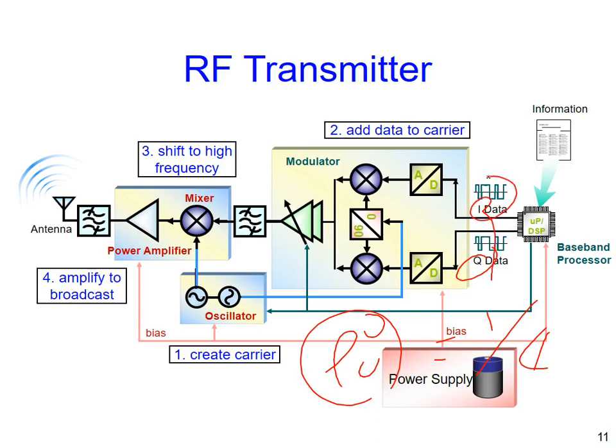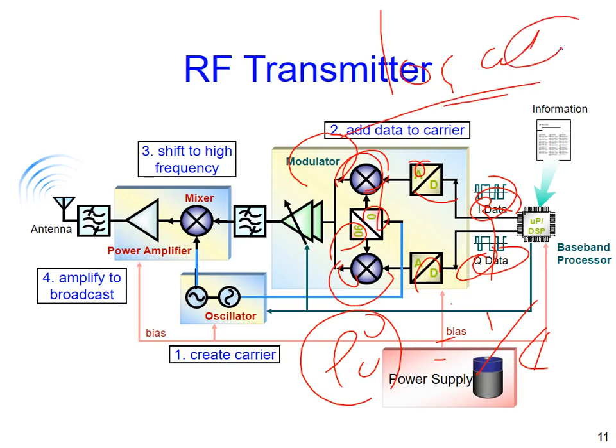That's it. Anyway, you still have data in the digital domain. I told you already, everything in the air should be analog instead of digital, right? So you need such kind of DA converter, digital to analog converter. Then you can see 0 degree, 90 degrees. You have such kind of mixer, 混波器. So how can you make sure your mixers, we call it local oscillator, 本地振荡器, can generate 2 signals with exactly the same frequency but 90-degree difference in phases?